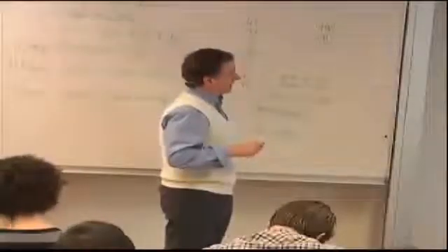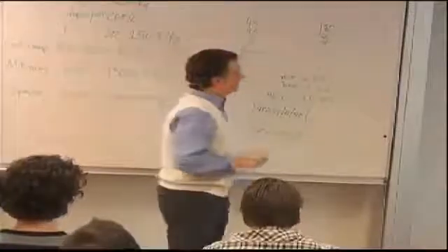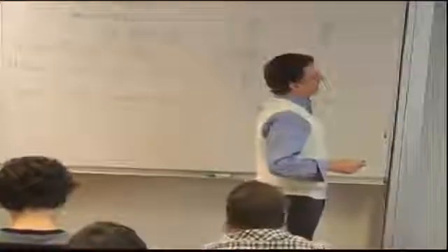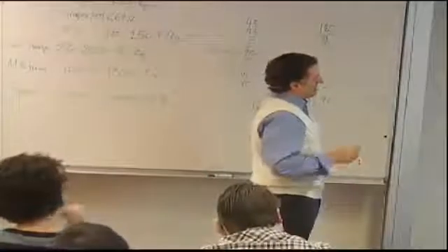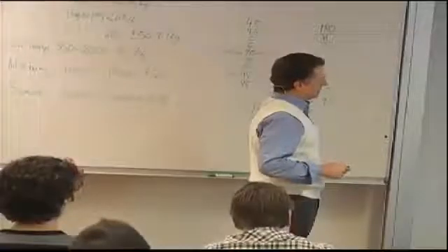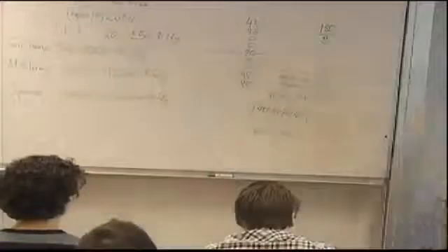So that was just a parenthesis, because I keep mentioning quasi-isotropic, and I meant to say that's one way of creating quasi-isotropic laminates. Stress-strain equations. This is the forces, and this is the A matrix with A16 and A26 equal to 0. So we get this set of equations. And if I divide by the plate thickness capital H, then Nx divided by h, as we said last time, is sigma x, and this becomes sigma y, tau xy. And then all these just get divided by h.